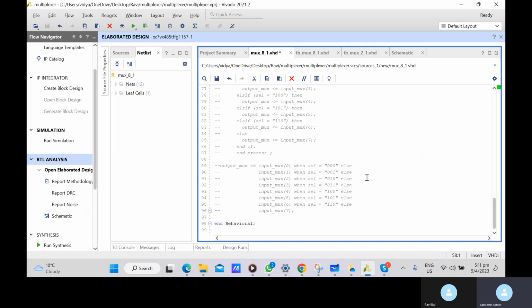If you have as many conditional statements as possible in parallel and you write a case, it will give fast hardware. So you should know when to write a case and when to write if-else. You should have a prior thought before writing the code.